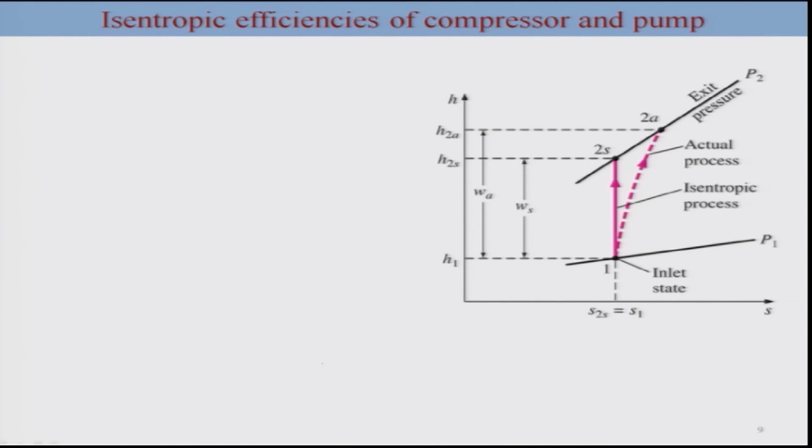For the case of a compressor or pump, the initial pressure is going to be low, and along the process, for isentropic process for the idealized where there is no irreversibility, okay, where there is a constant entropy. So we are assuming that the actual and the idealized compressor, the exit pressure is same. So this is your total work for the case of idealized or isentropic process.